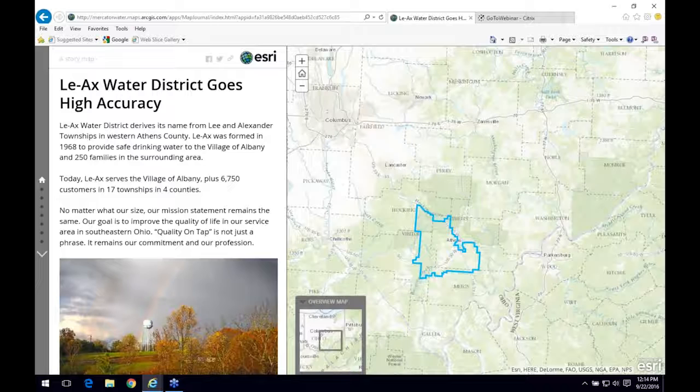We have 2 groundwater wells that are close to the Hocking River. That's the major river that flows through this area. The Ranney collector wells, one is 9 foot in diameter, the other one is 13 foot in diameter. And then at the bottom of those wells, there's laterals that go out and collect the groundwater.